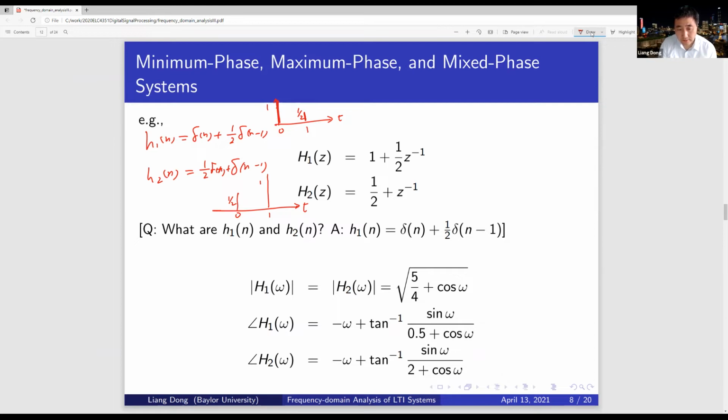We also notice here, now compare these two systems. Which filter is a better filter? It's hard to say, but just by looking at those two delta functions, maybe H1 is better because the delay path is smaller. I want to concentrate the energy at the non-delayed path, or concentrate the energy of the filter as close to 0 as possible. Therefore, I don't have a heavy delayed tail.